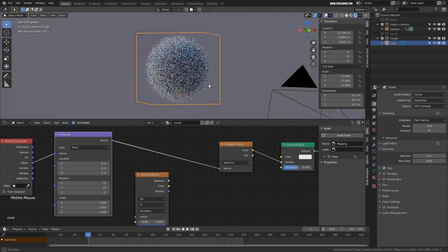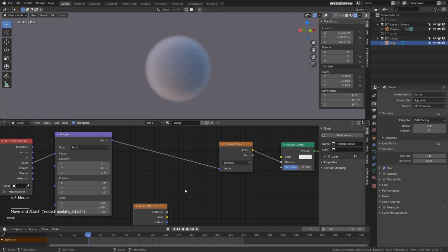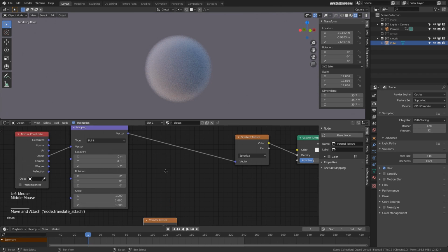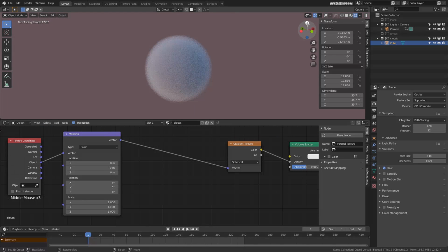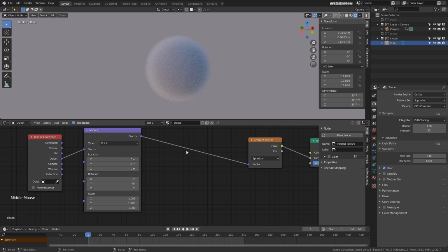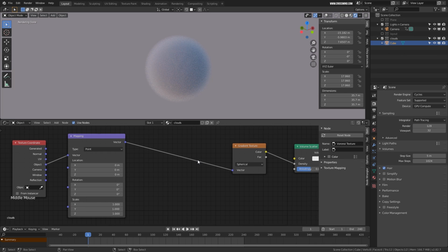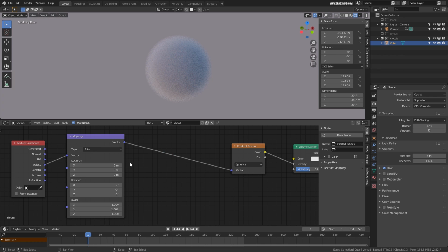Okay, and there is one more interesting thing you can do. This I had seen in the CG Geek tutorial, and it's a very interesting approach. You can see they have an entire tutorial on just how to make clouds. So as you see over here, the Z direction is represented in the blue, and the X direction is in the red, and the Y direction in the green. Okay, now RGB and XYZ, these are vector coordinates. Okay, and actually you can use these RGB values to influence the vector inputs. Okay, like XYZ in the rotation, location.